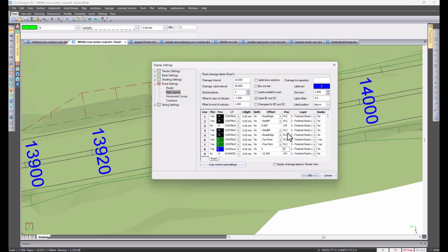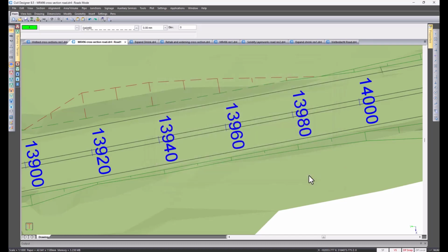Okay, so there's three options. Traditionally with these cross-section roads was the offset, point location code, the PLC, or an ID, and then that ID would be number 1. Okay, and then we're plotting that line. The program will pick it up with the ID number and then position it in the plan view. Okay, so you can see there the middle of your V-drain has been plotted.